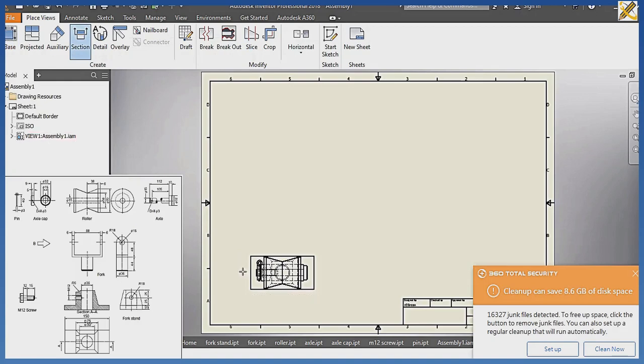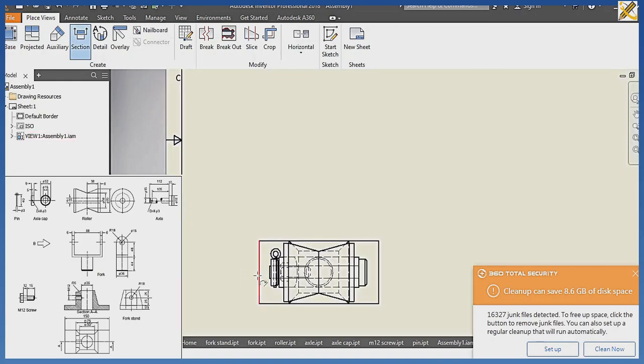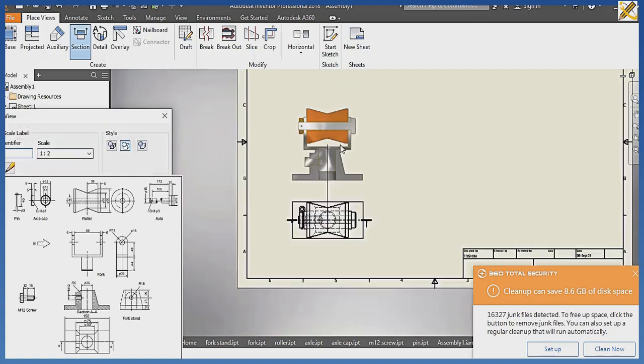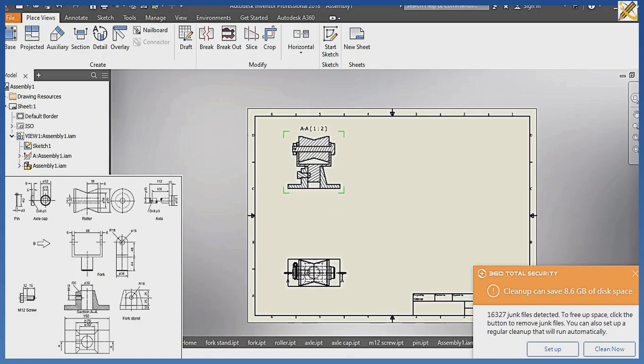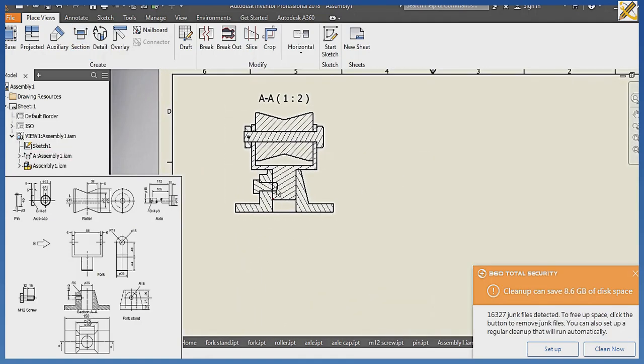With my okay, I pick section. With my section, I click right here. Okay, then locating the center, which is this. I drag this downward, facing the top. Then continue. So I'm having this right about now, right here. Okay, now having that, I'm going to hide this. Just like I said, we don't section boot, so I'm going to hide this.